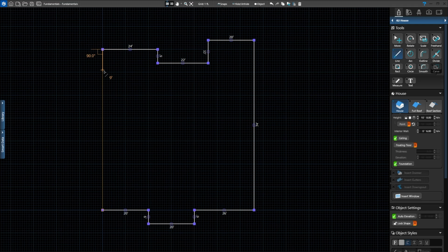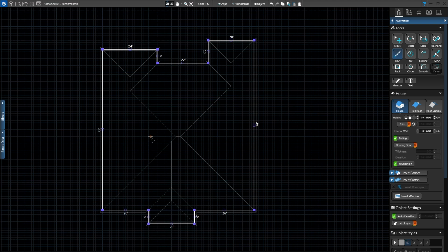If I know that that's how I want to complete my shape, I can press enter and it will auto-complete my shape. So it's just a way for the system to suggest that this is a path for closing your shape. If you drag the line down and left click, that closes your shape as well. Or again, if you press enter, autocomplete will complete your shape for you.